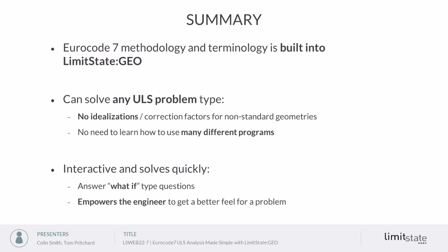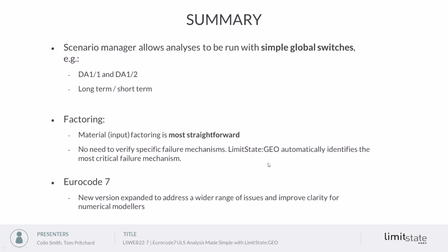It's interactive. I haven't been able to show you that much here, but hopefully you've seen it's quick. We can edit the problem quite quickly, and we can answer what-if type questions. In the scenario manager, we can run different analyses with simple global switches, such as switching the partial factor set, or switching from long-term to short-term, or drained to undrained analyses.